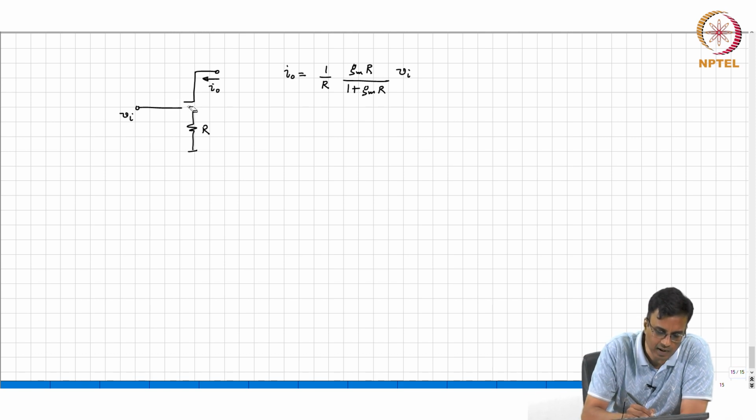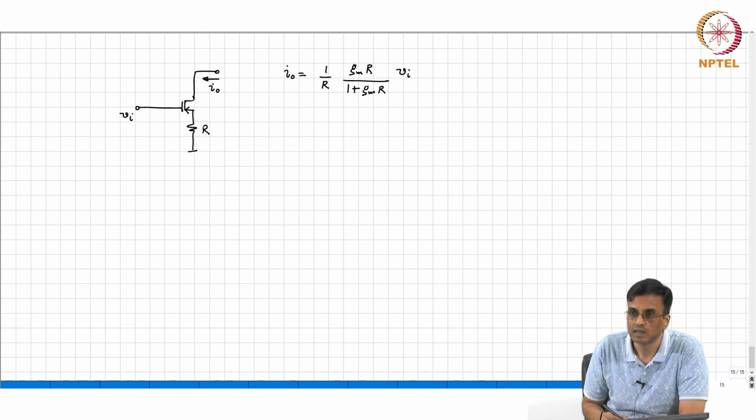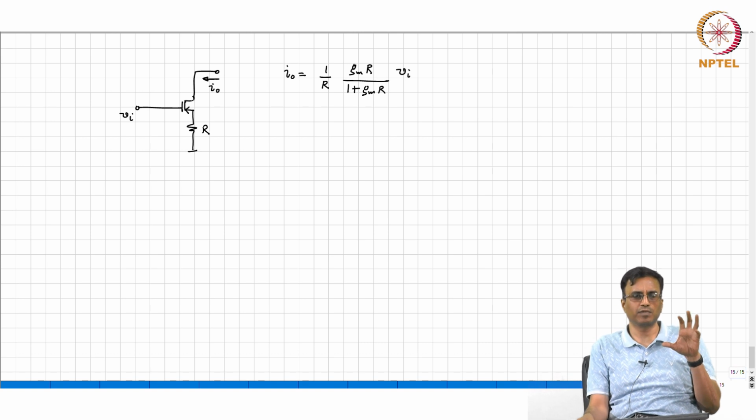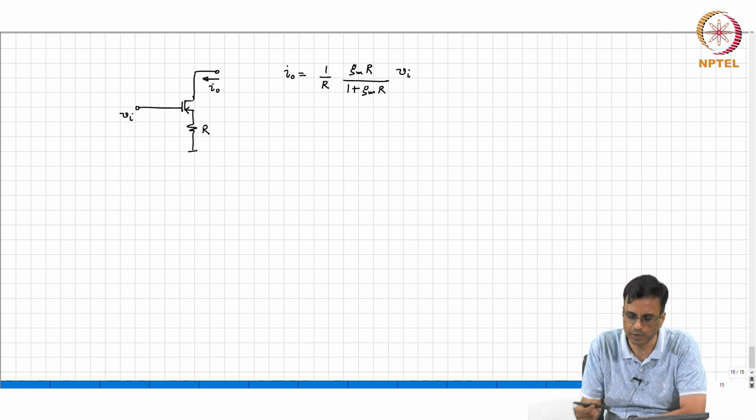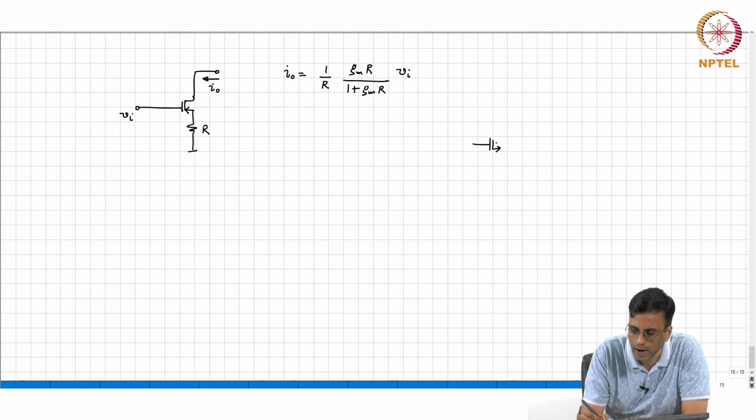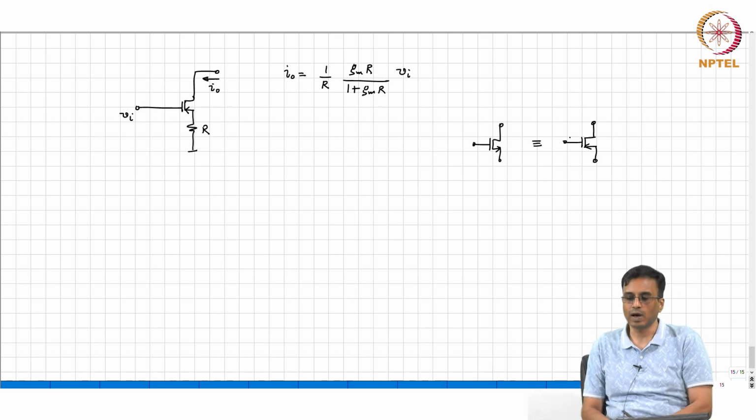I mean, in the incremental circuit, nothing is to be done other than changing drain and source. It is just changing only the direction of the arrow in the source, right. Remember that the incremental models of the NMOS and the PMOS are exactly the same. So, as far as the incremental circuit is concerned, if you had a device like this in the incremental equivalent, it is exactly going to be the same, assuming the PMOS transistor is biased properly. Whether you have this or that